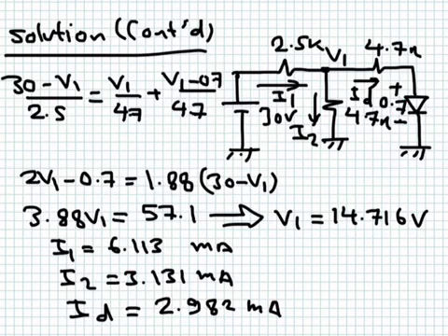So the voltage across the diode is 0.7 volts, but the current through it is 2.982 milliampere. What determined that current? It is simply the surrounding circuit. Okay, so this diode indeed has to be on, and it is sinking this current, 2.982. So this current is flowing from the anode to the cathode, and the diode is in the forward direction.